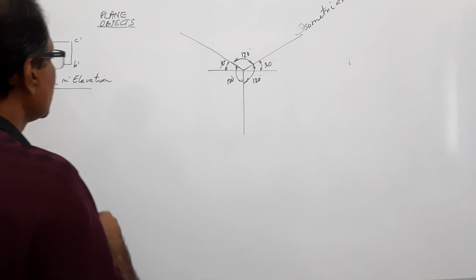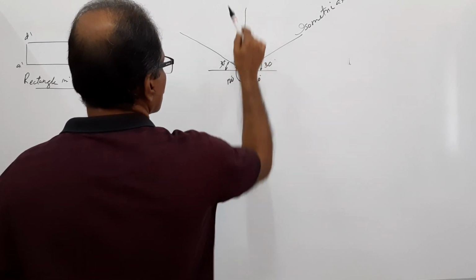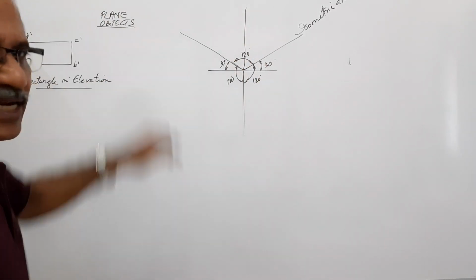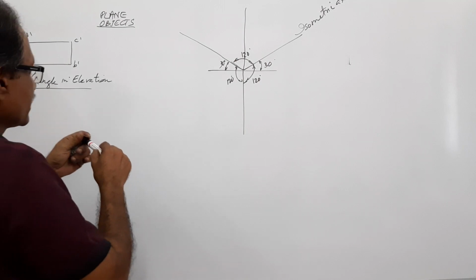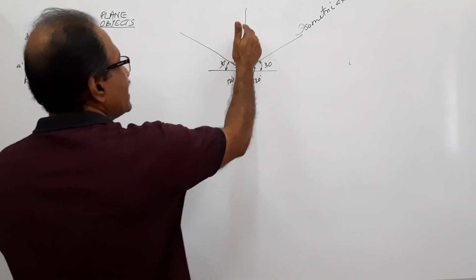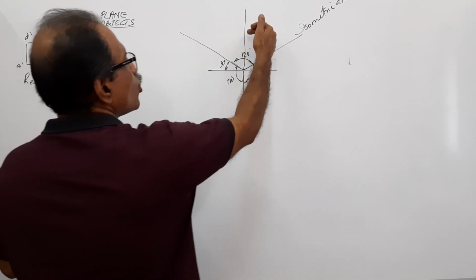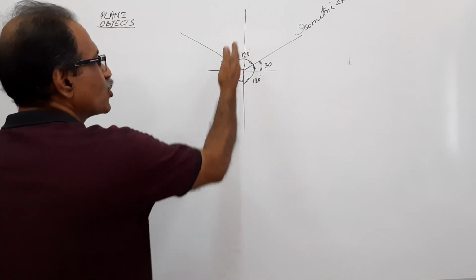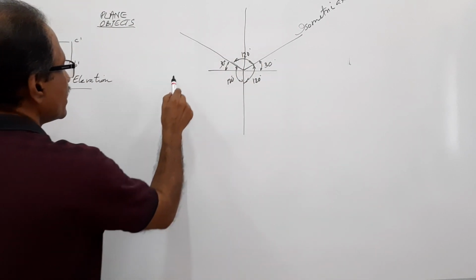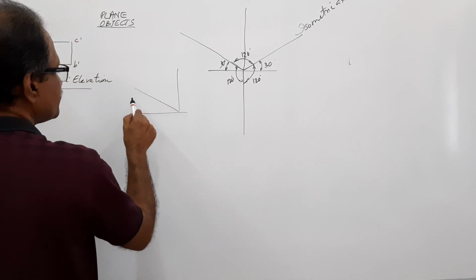What you do is, this vertical axis, extend it upwards also. We can draw the isoview of this rectangle either in the plane constituted by these two axes, or between these two axes. I draw it to this side, this plane. I draw a vertical line, then I draw a 30-degree line.